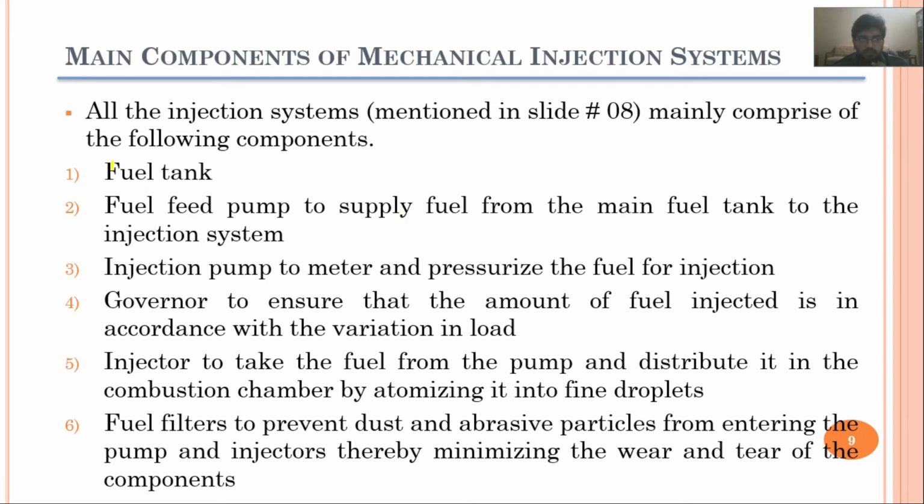So the first important component is the fuel tank, where your fuel is stored. Then there is a fuel feed pump, which takes that fuel from the main fuel tank to the fuel injection system. And this fuel feed pump is increasing the pressure of the fuel, but these are low pressure pumps. They are not increasing the pressure that much.